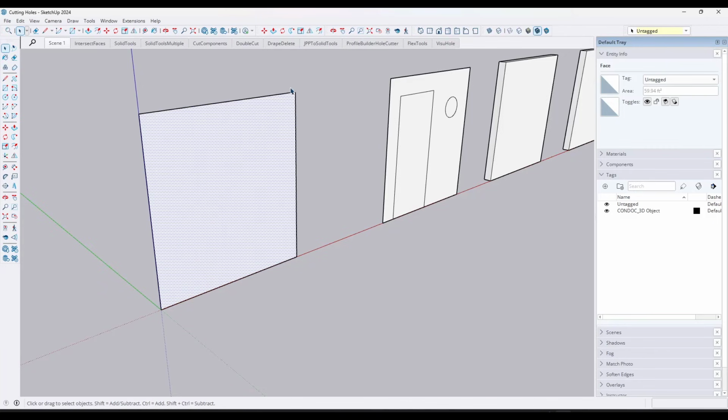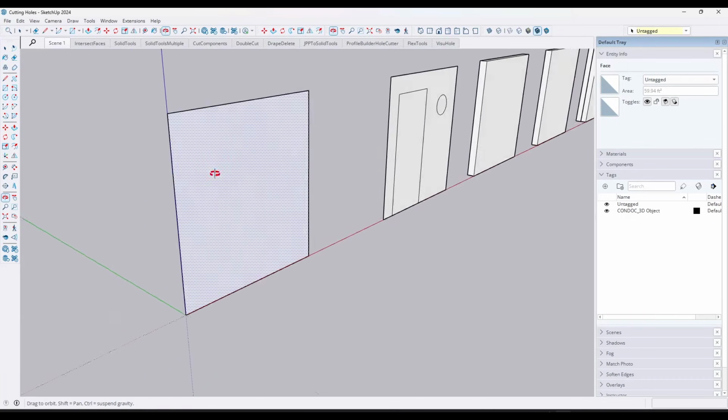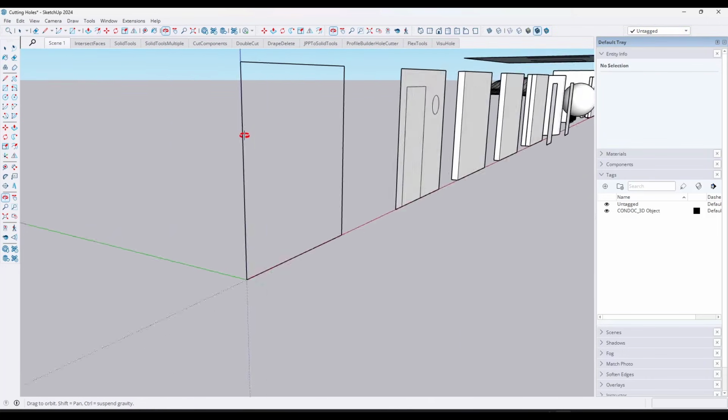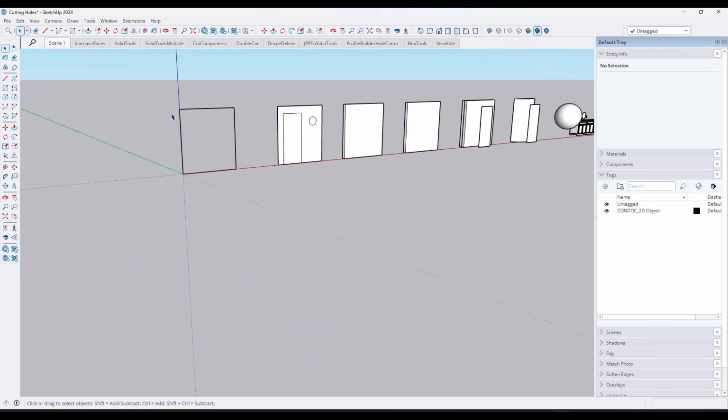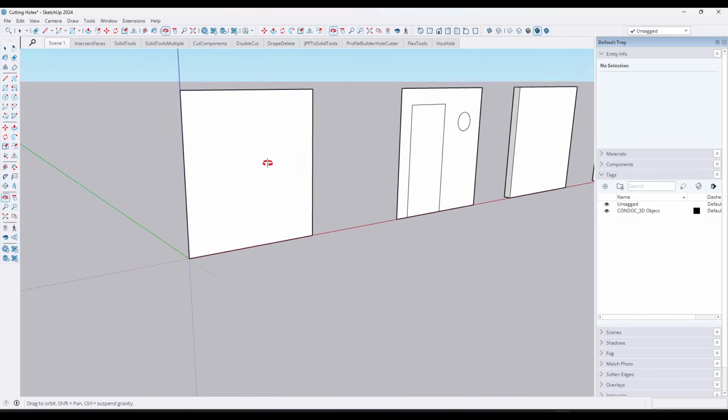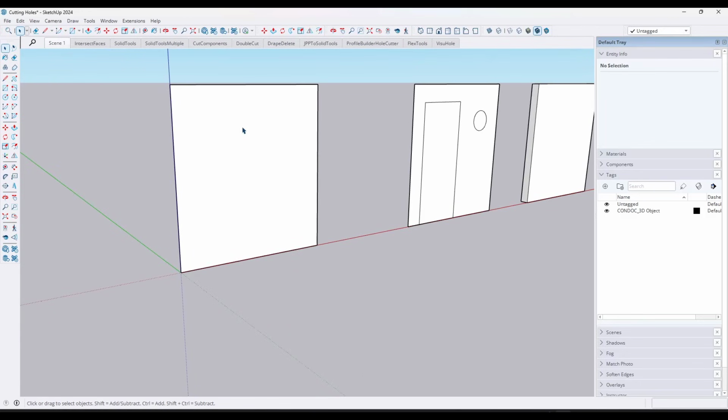And so remember that basically the way that SketchUp works is you have faces inside of edges. And so when you get 3 or more coplanar edges, SketchUp creates a face, right? And you can delete out these individual faces. So if I was to select this, tap the delete key right here, notice how I'm able to completely delete the face in here. You can heal the face back in by drawing over one of the edges. And so anytime that you remove one of the edges and there's no longer any kind of a closed shape in here, you're going to lose the face.